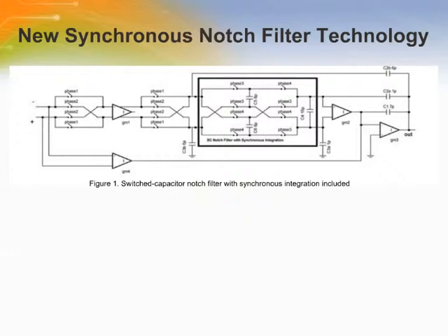Texas Instruments introduced a zero-drift chopping topology to solve these problems. Instead of the noisy odd-order harmonics, TI designs incorporate a proprietary synchronous notch filter to attenuate the chopping noise inherent in the zero-drift design and filter out the odd-order harmonics. The result is that the chopping noise is reduced to far below the broadband noise of the amplifier. TI's zero-drift products achieve industry-leading noise performance.